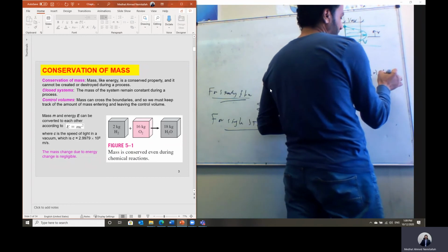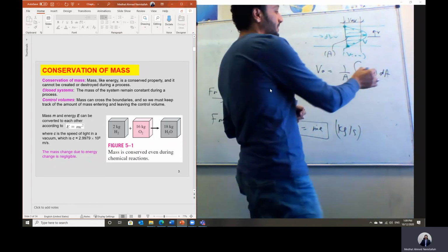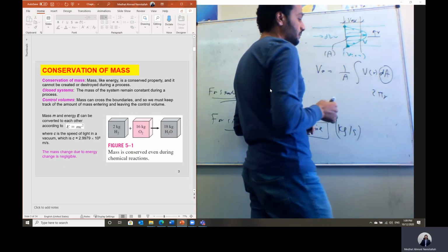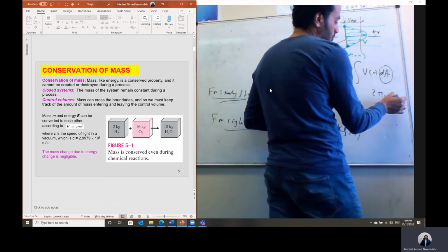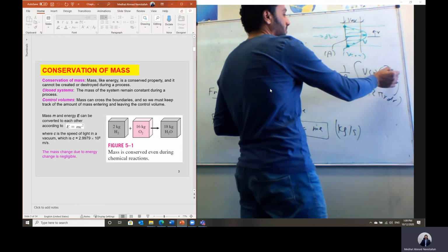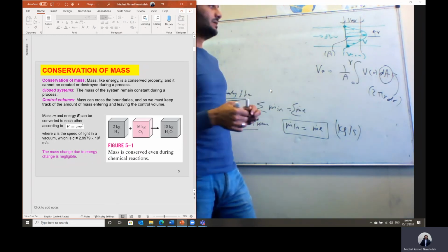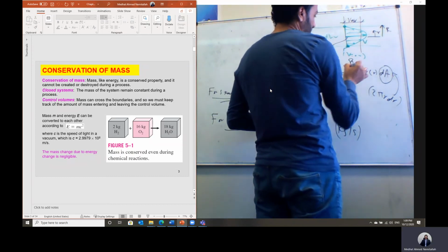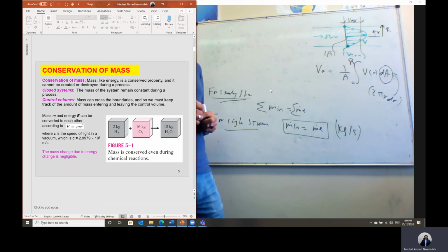It's a kind of parabolic function, integration of delta area. Delta area for a tubular cross-section is equal to pi r squared. So differentiating, delta area will be equal to 2 pi r dr. Then we can substitute here the integration of dr from 0 to the radius of the tube. The radius is the outer radius here, let's say r capital. So from 0 to r capital, we can calculate the average velocity in this case.